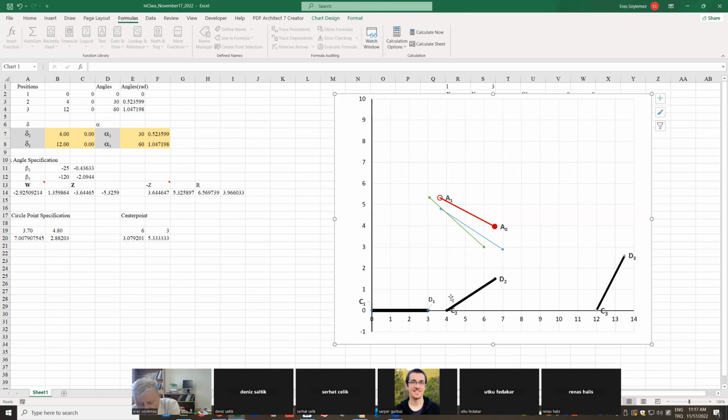And then you have to check the transmission angle. And then you have to check whether there's an obstacle. Or then you have to check whether you can design it or not, or lots of things. But basically the procedure is you have to use this formulation and then check your results, see that all your other conditions are satisfied.